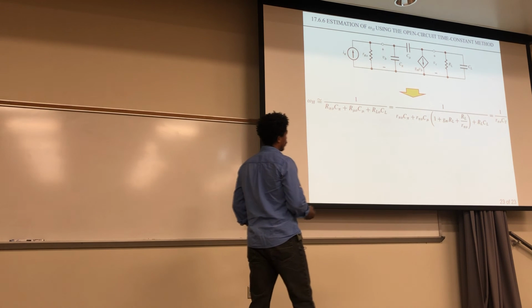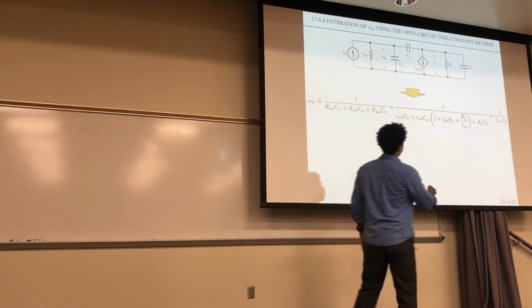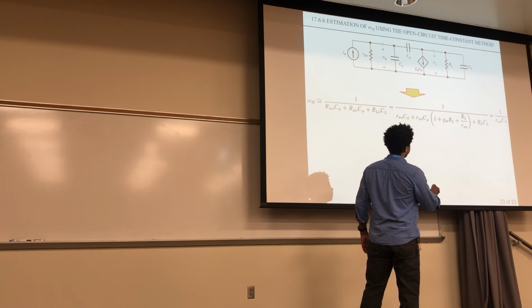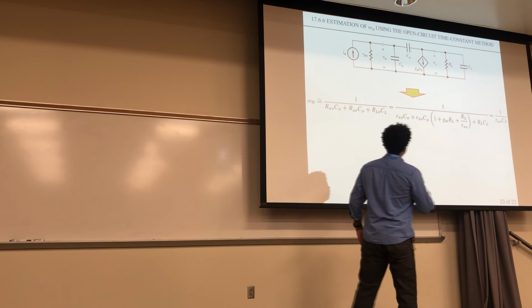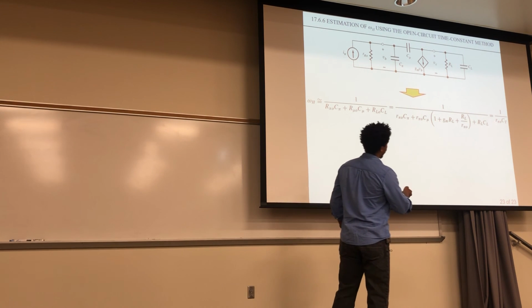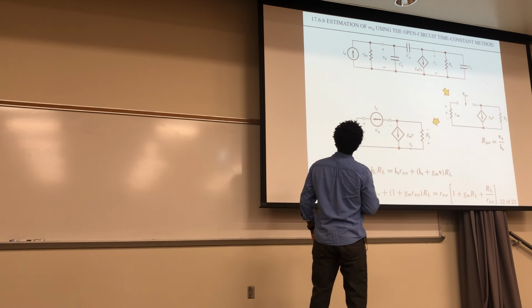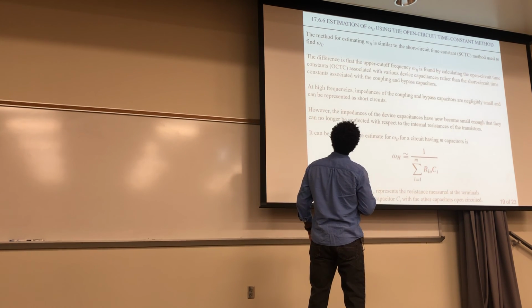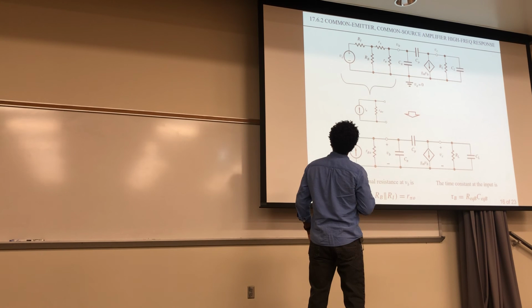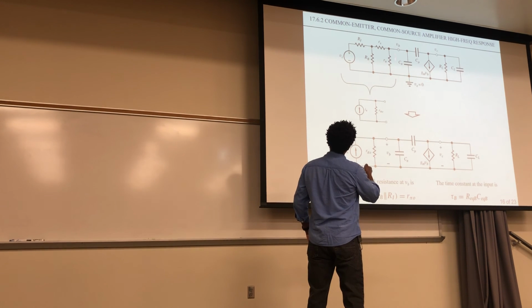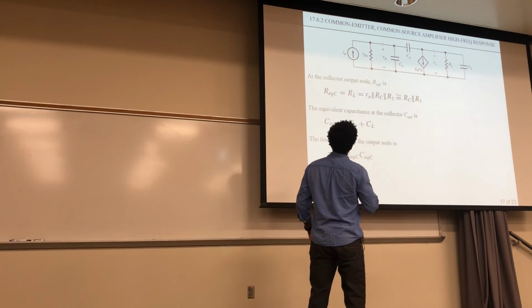And what you can do is reduce this to this expression, and this CT is what you get if you factor out this R pi 0. Remember, R pi 0 is right here, which was, let's put it back there, all this stuff. All this stuff is R pi 0 from your input.